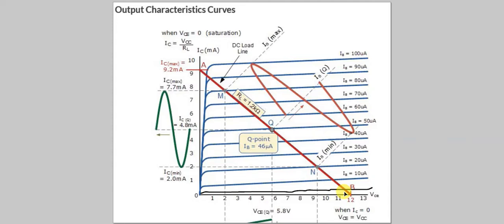the transistor. This region may go up and down because of generation, since the transistor is made from crystal, germanium or silicon. Its intrinsic property is that at room temperature, the electron hole pairs are continuously generated. Recombination and generation is going on with the temperature. So what the scientists do, normally in a normal amplifier, class amplifier, it is supposed to be not varying. The Q point, we suppose that it is fixed, it is not going up or down, but practically the Q point is oscillating a little bit, but small.